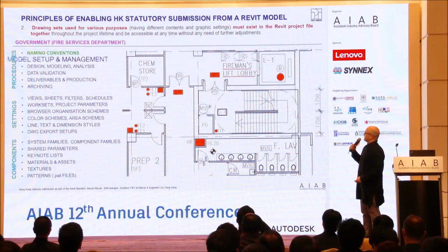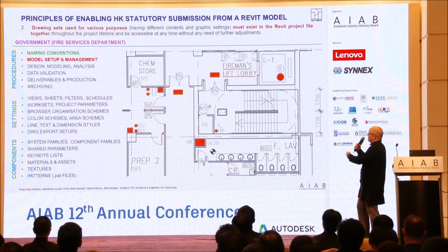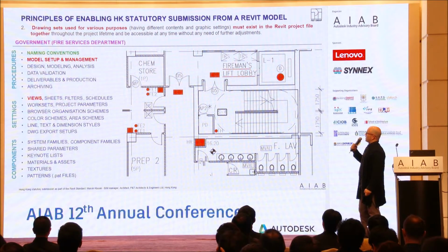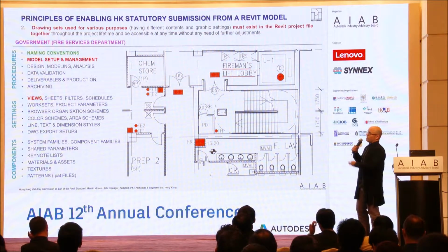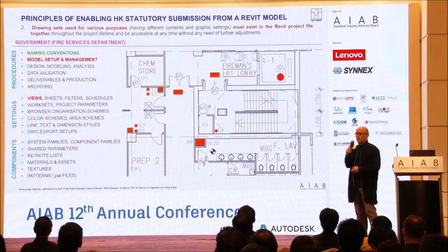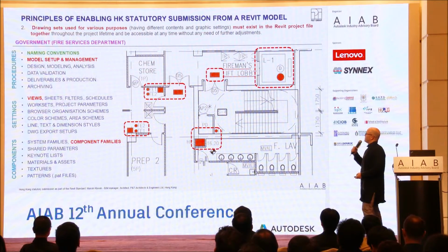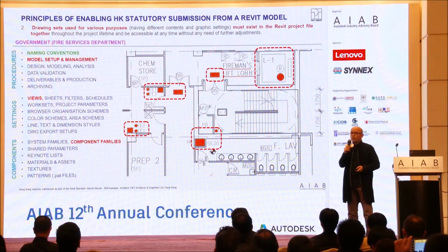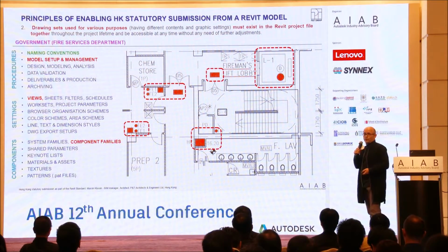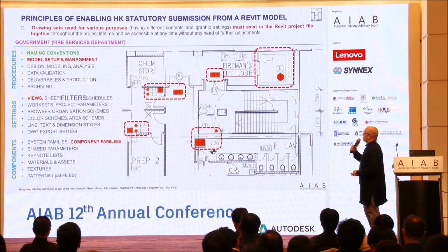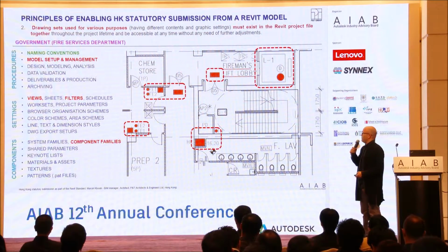To achieve a result like that, we need to standardize our model setup and management to basically build all this. Then have predefined views, which will be responsible for these graphic layouts looking like that. Views include, obviously, view templates, one of the most important things. Component families, which behave in a certain way when they are treated by a certain view template, basically displaying the orange background. And filters, which need to be applied to a view to result in such behavior.